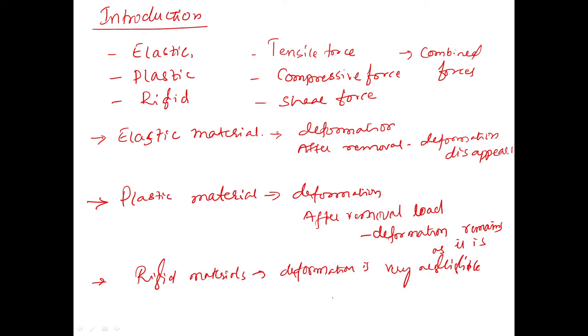Now, as I said, if you consider the mechanical components, they are subjected to different types of forces or loads: tensile force, compressive force, shear force, and combined forces. For example, a connecting rod in an IC engine is subjected to tensile and compressive forces.